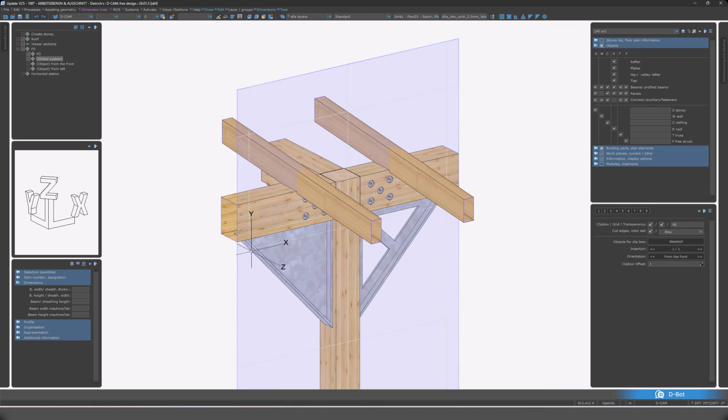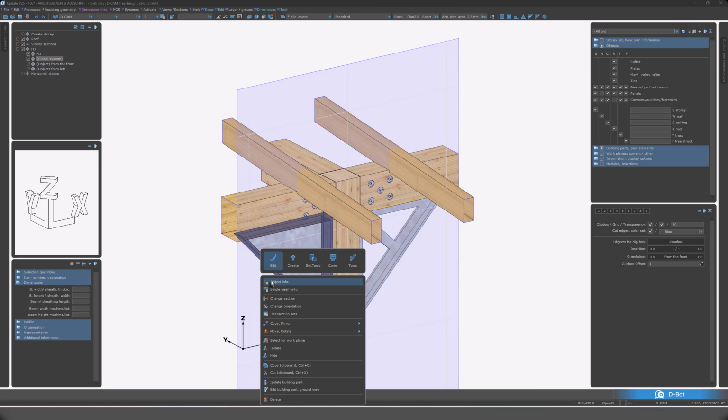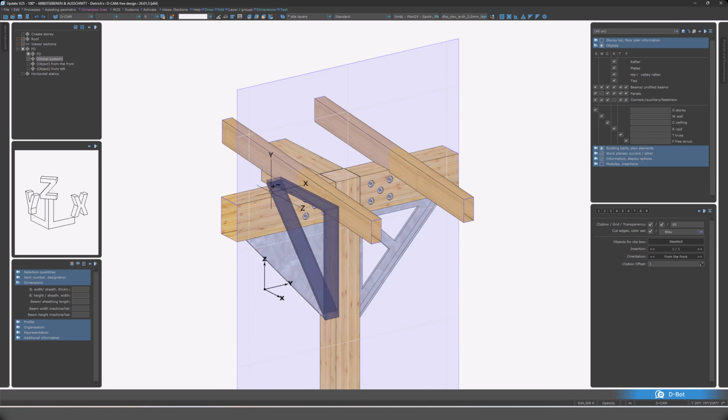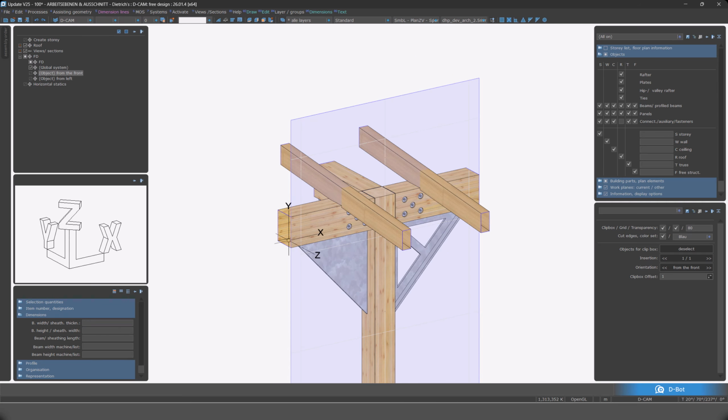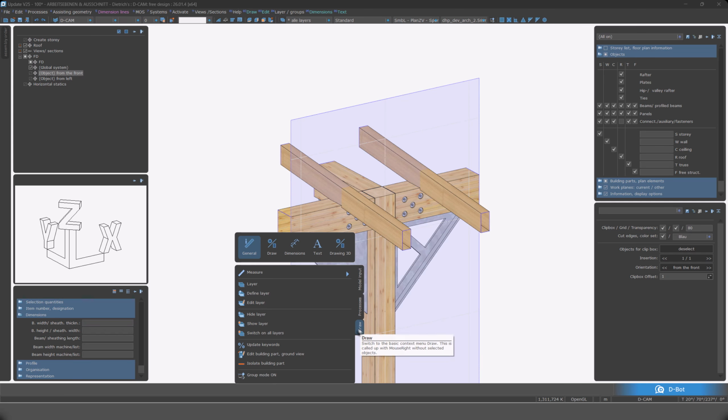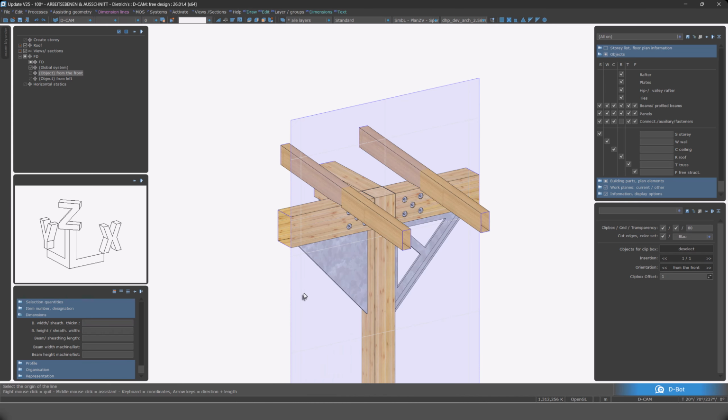So I'm going to turn off one of the components here on our bracket. On the rear bracket, I'm really not concerned about that just because we don't see it right now. So I'm now going to go ahead and reproduce these lines from this component and projecting it onto the grid here. In version 26, I can now use this draw function down here. Lines, line. And you can now see as soon as I move close to that component that these lines are being projected onto the work plane.